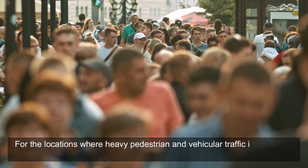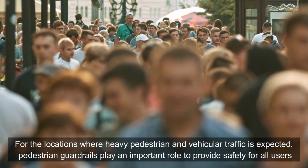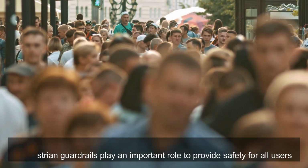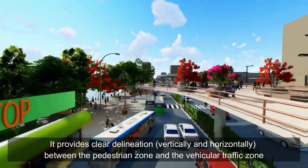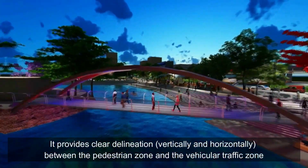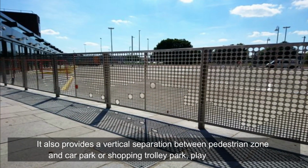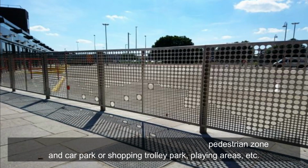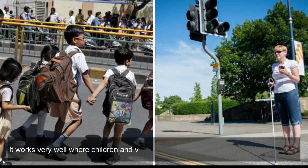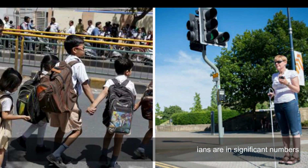What is the purpose of pedestrian guardrail? For the locations where heavy pedestrian and vehicular traffic is expected, pedestrian guardrails play an important role to provide safety for all users. It provides clear delineation, vertically and horizontally, between the pedestrian zone and the vehicular traffic zone. It also provides a vertical separation between pedestrian zone and car park or shopping trolley park, playing areas, etc. It works very well where children and vulnerable pedestrians are in significant numbers.